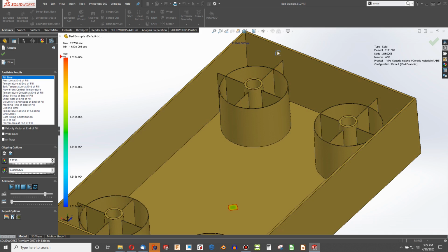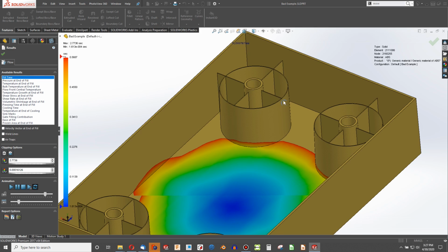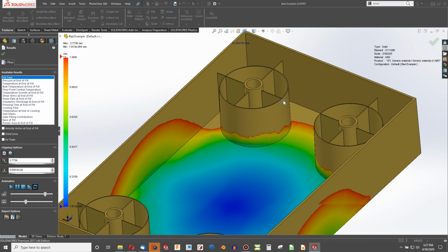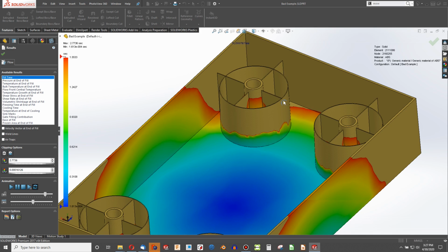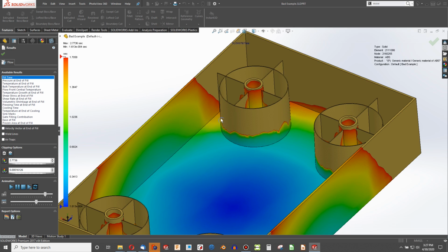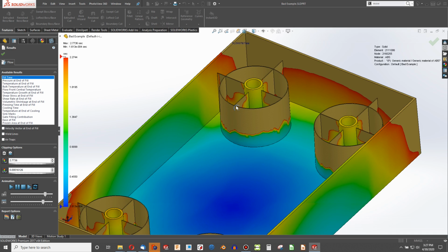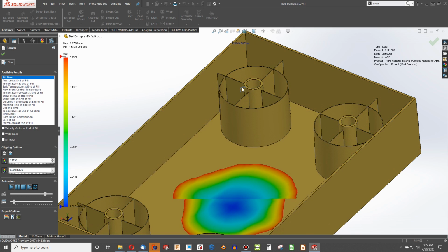And then finally, the last flow front kind of comes up from the back and fills everything else up the rest of the way. That is horrible. That is truly a failed fill. You don't want to have this kind of hardening and then go back and fill over it. It's just not right. So this is a failed mold, and this is an example of what can happen when you don't follow the rules.